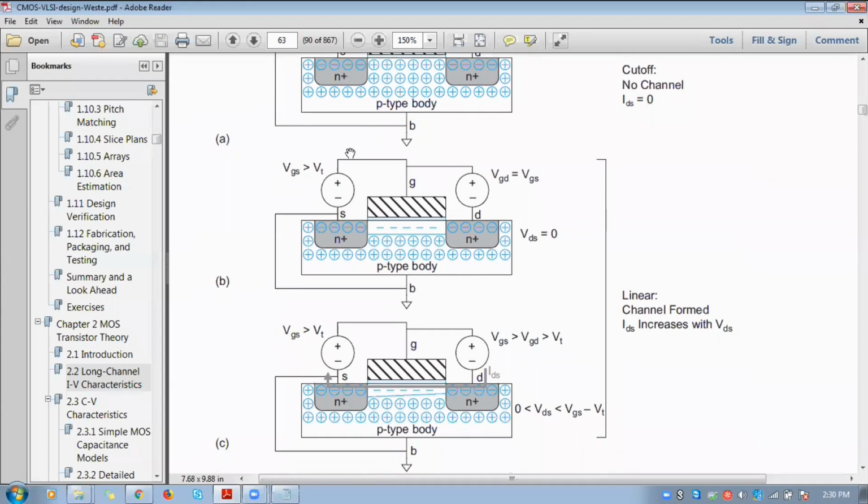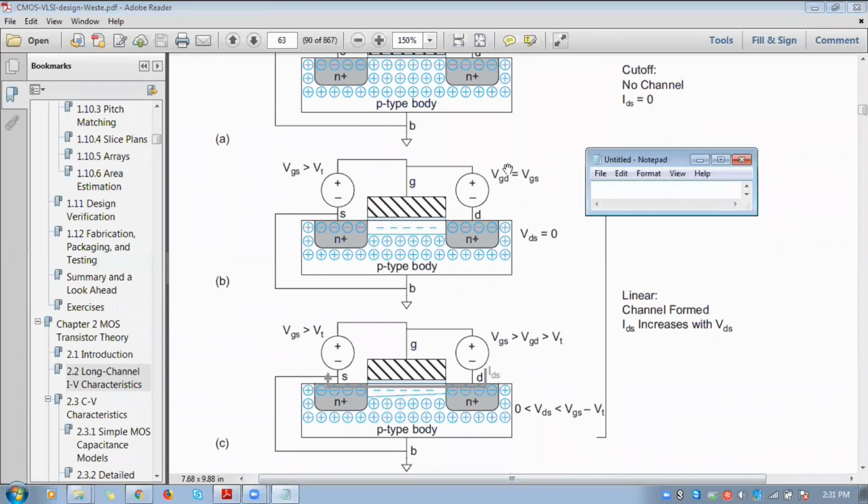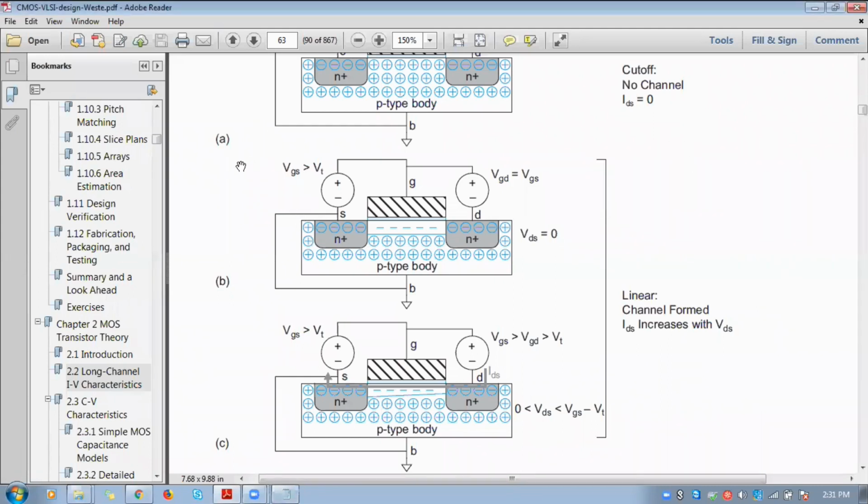And the voltage conditions will all be reversed. Here VGS should be less than VTP. Actually, you have to specify the suffix also. You have to mention it as modulo minus VTP, instead of VTN. Wherever you see the threshold voltage, that has to be replaced with modulo minus VTP. We will be taking only the magnitude value of the threshold voltage in the case of pMOS. So that should be VGS less than modulo minus VTP. This condition is the same. VDS is also equal to 0.